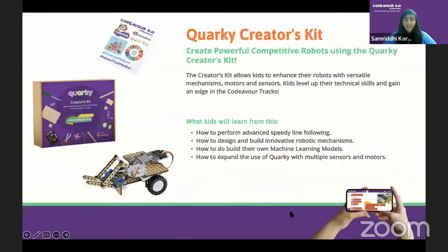Now, moving on, let's see a really fun thing, Quirky Creator Kit. Have you guys used it? So also one more important thing I forgot to mention to you guys is whenever you're buying an electronic component, get it from an authorized dealer. Okay. So getting the right components which work is more important to build a project. Or else the debugging phase will be longer until you realize that your component is the faulty one, though your code and connections are perfect.